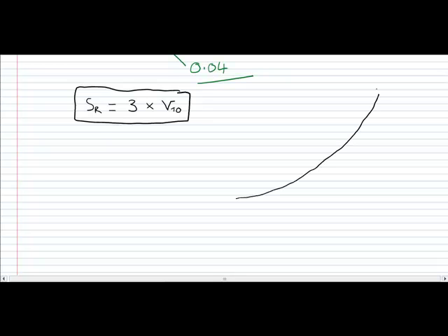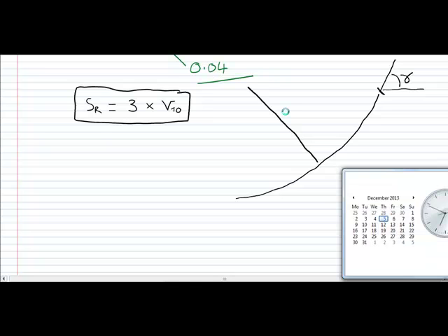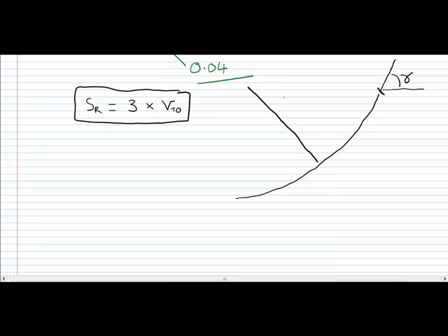Okay, and I've obviously exaggerated the flight path angle that the aircraft's going to end up going at. That's usually we'll let the flight path angle be gamma. So at this point here it carries on at a constant climb rate, constant flight path angle, and up until that point it's been going round what we'll assume is a circular arc of radius, we'll call that radius R transition.